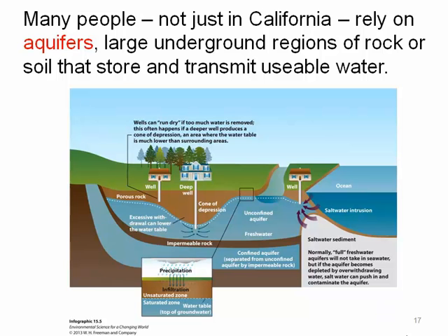In the figure you'll see on this slide, you'll notice that there are different layers: unconfined aquifers that rise and fall with inputs of water and pumping, and confined aquifers that are deeper and under pressured systems. All of these can interact with and be affected by saltwater intrusion, but most prominently in the shallow unconfined zone in coastal regions, where overpumping may lower the saturated zone such that the higher water level in the ocean will cause water to flow inland.